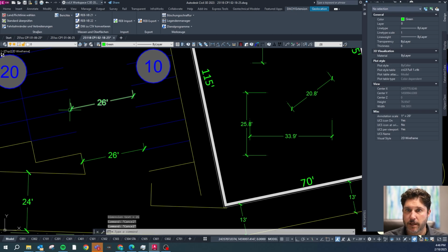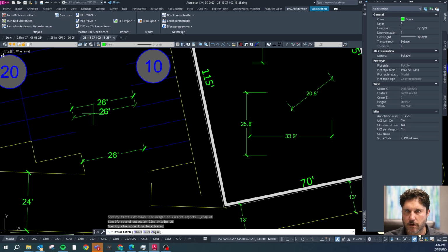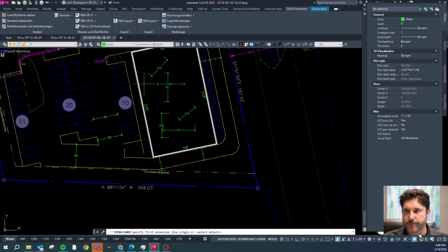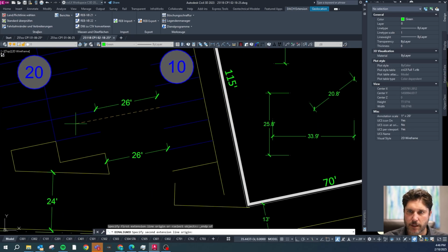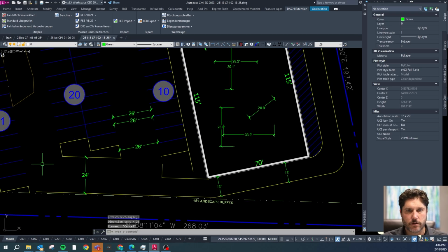So if you ever see you're drawing a certain dimension, it's not showing up that dimension, check your elevation, and it could be that the elevation was off. So I just go in the direction I want to go, type 26, space bar, and there I have a dimension in the proper direction, even though there's nothing to snap to the perpendicular of. And that's a quick tutorial on dimensions, and that's it for today.